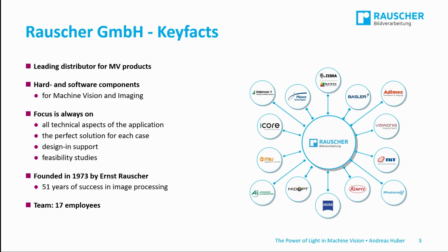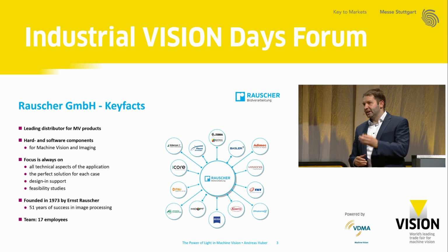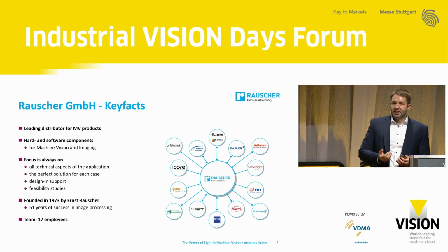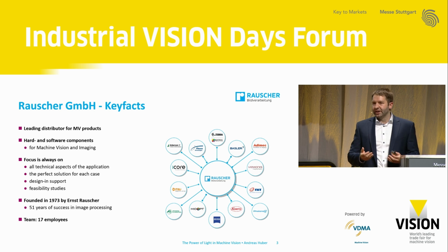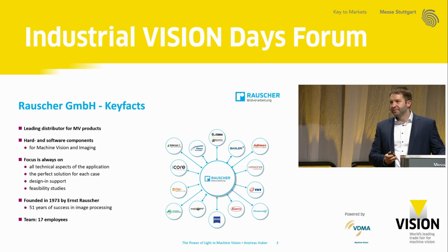Sometimes, especially when it comes to light, the application is very hard. For the camera, you can calculate how many pixels you need, how big is my defect, which accuracy do I need, so I can do some calculation and choose the best camera. But when it comes to lighting, you need a lot of experience, a good feeling. Sometimes you don't know how your product behaves in UV or SWIR lighting. So with some special lights, you can get a much better result in your application.